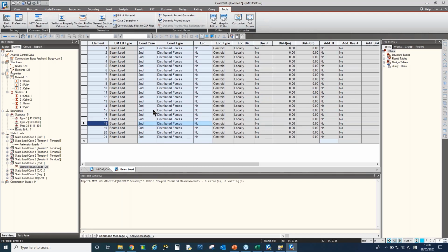So the load cases have the information about the element number to be applied. If two models have different element numbers, and you bring it to a different geometry model, then it might show awkward loading.